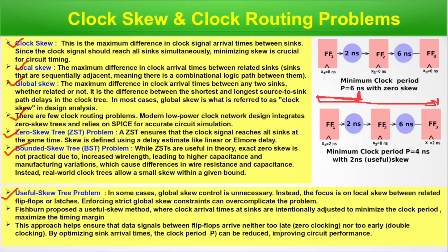This ensures that data signals between flip-flops arrive neither too late, that is zero clocking, nor too early, that is double clocking. By optimizing sink arrival times, the clock period P can be reduced, improving circuit performance.